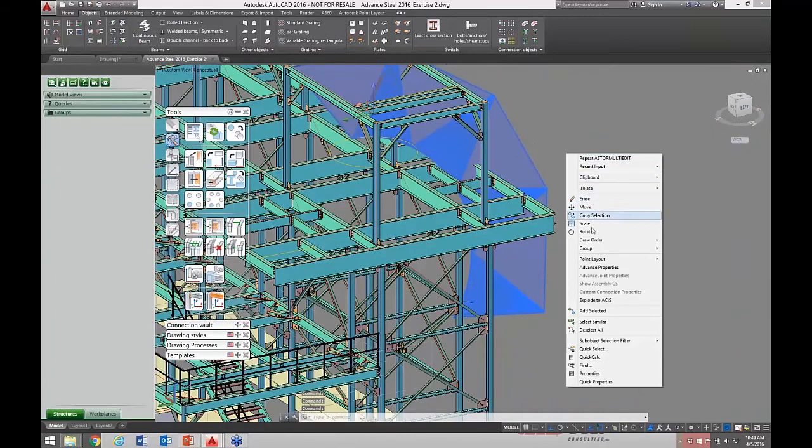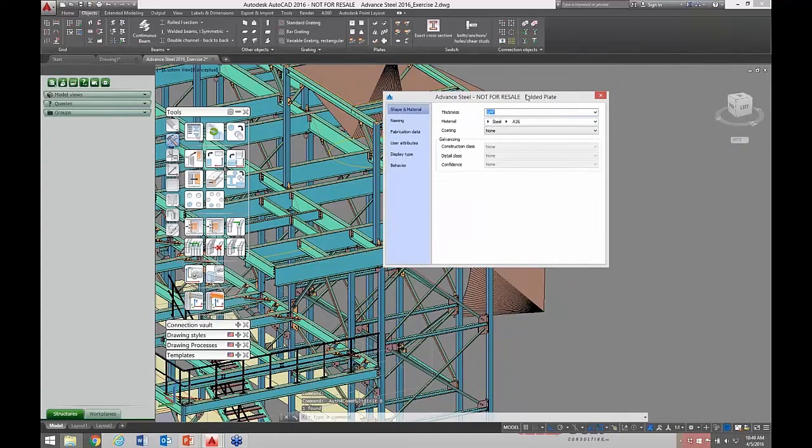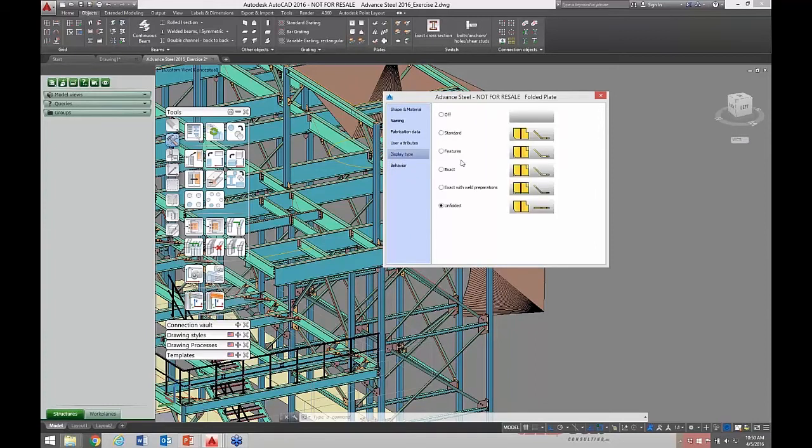You also have the capacity in similar fashion that if we have circular columns, beam members that we need to unfold, if we have a cut, skewed shape, something that maybe gives us an elliptical or parabolic shape on the end of a column, for example, or a tube brace or something, we can unfold those items to give us patterns that we can utilize to make that a little easier to fabricate in the shop.